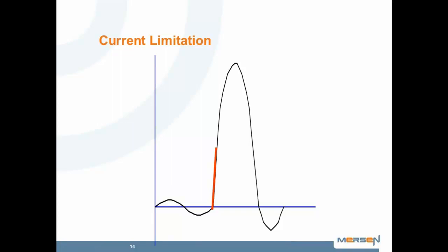If we extend that a little bit, the fuse will cut off the current provided that it's in the current limiting range, and bring the current down so that it's completed clearing by the first half cycle. And according to the definition from the National Electrical Code, it has substantially reduced the current flowing in the first half cycle.